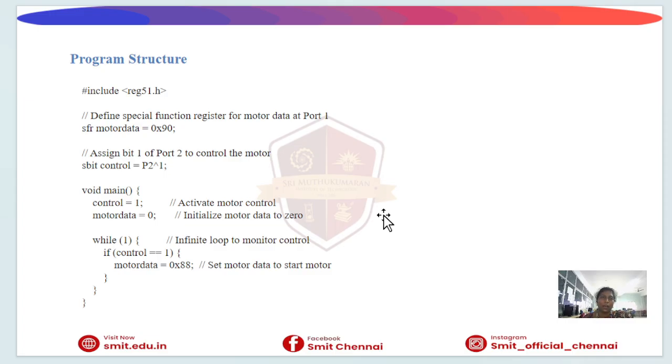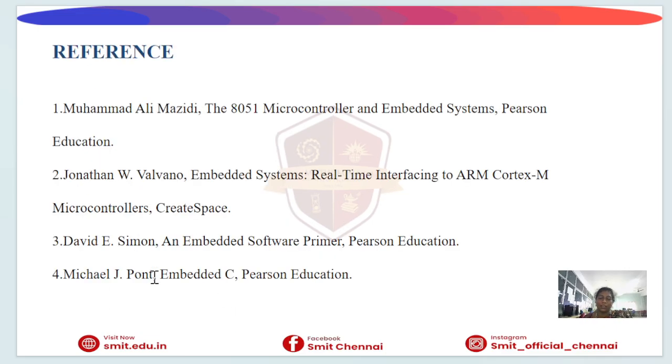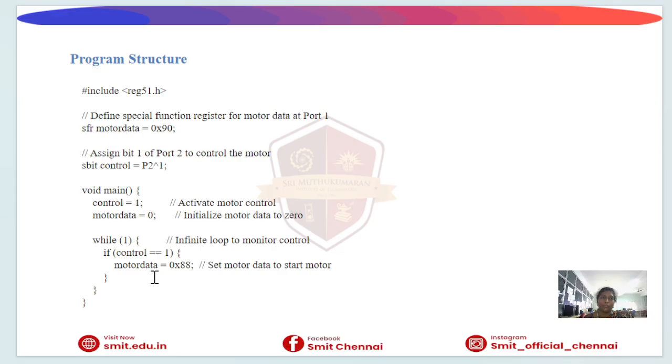This is a program used for the control and the motor data. While the control is equal to 1, the motor will start to rotate. The function of the driver circuit is to amplify the current, protect the microcontroller, and provide safe switching. Now the program structure: reg51.h includes the 8051 definitions, and the motor data refers to the port 1 definition. The control is connected to the port 2 definition.